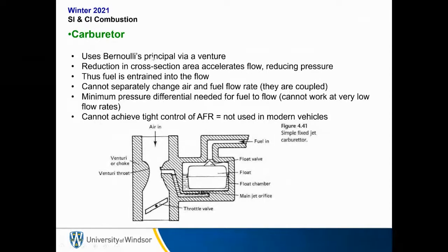So what's a carburetor? Well, it uses the Bernoulli principle via a Venturi to suck fuel into the air intake stream. So air is coming in, and there's a reduction in cross-sectional area that accelerates the flow. That means we get a low pressure area. This low pressure area entrains fuel from a different tube into the stream. So essentially it uses a Venturi to create low pressure and then suck fuel into the stream.